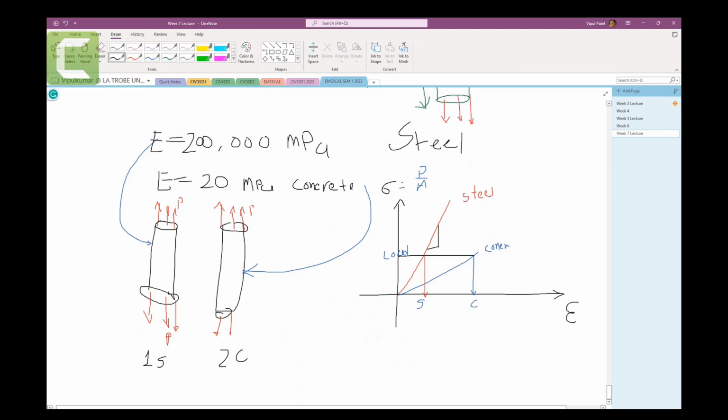So that is rise over run, like the stress. If you take this part, which is the stress, the difference from this point to this one, and the difference from this point to this point. So if you draw it, stress over strain will give me the Young's modulus. Young's modulus is equal to stress over strain, the ratio. Let's say this is sigma 2 and sigma 1. You can take the difference of these ones and the difference of these ones.